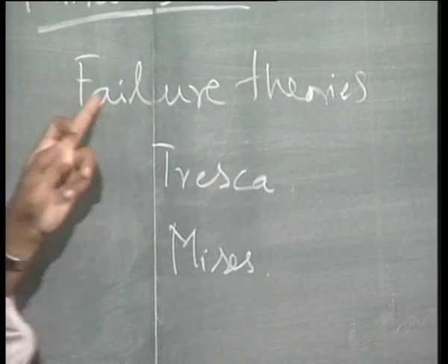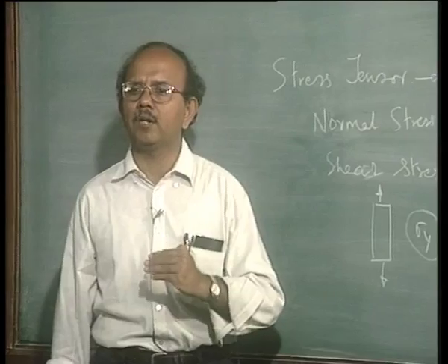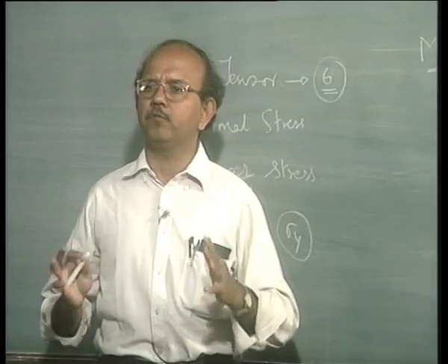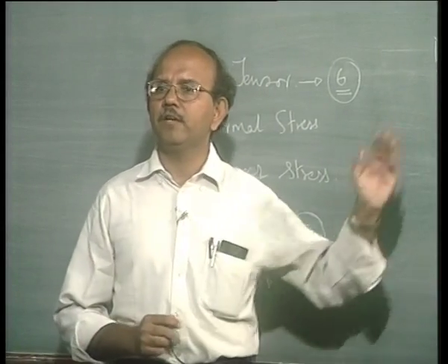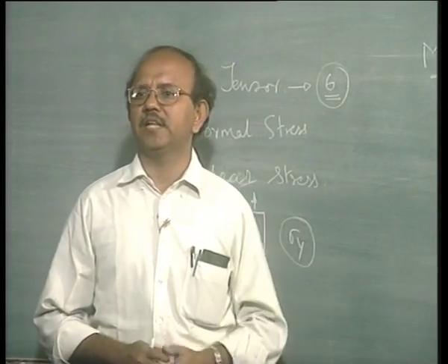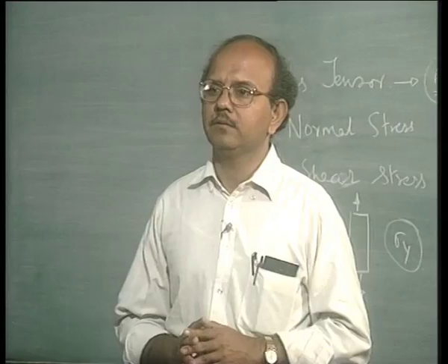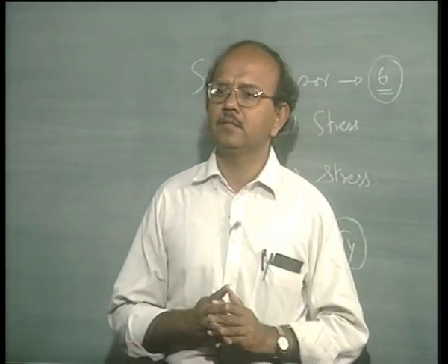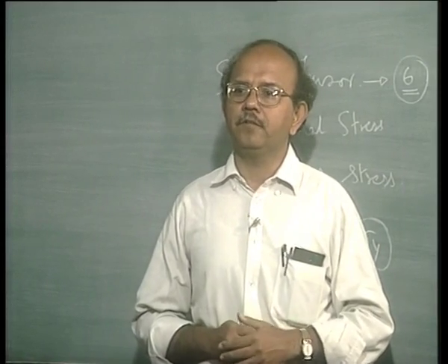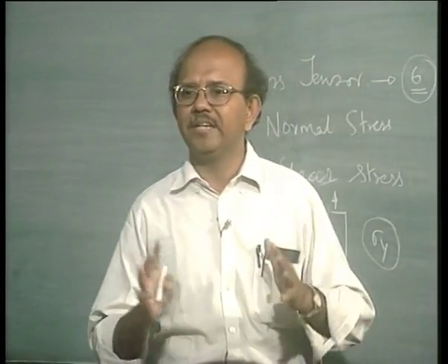Now, this term failure theories is a misnomer, and unfortunately students do not pick that up very clearly. Failure does not mean fracture of materials. A lot of people make this mistake. Failure theories do not mean that when Tresca's criterion or Mises criterion is satisfied, the material is going to break into two. No. For design purposes, it has long been assumed for 100 years now that if the material starts yielding, it will not serve the intended purpose.